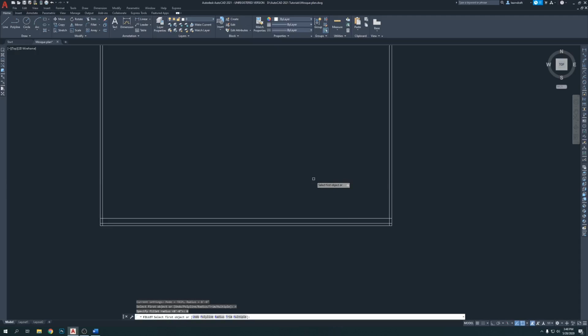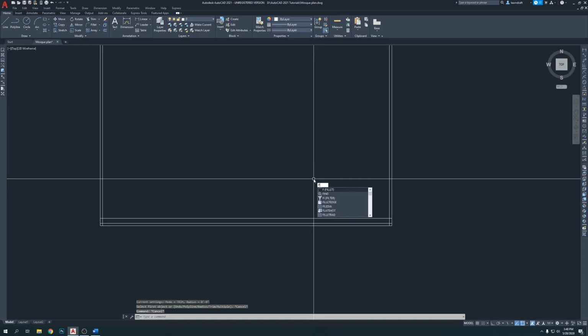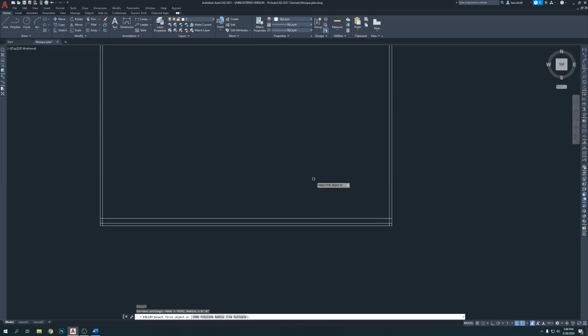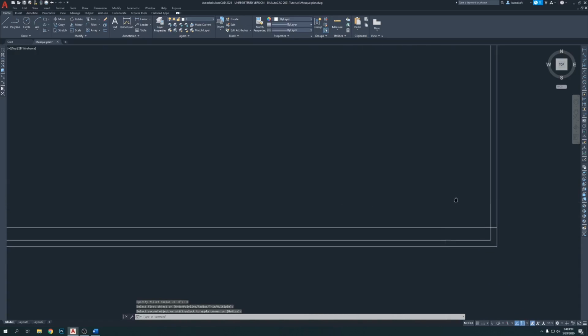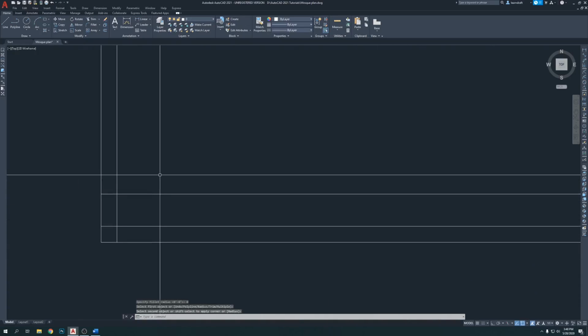Oh, I think I'm doing it very fast. Okay, fillet. Enter. F. Enter. Fillet, okay, from the beginning. So F, enter is for fillet. Radius, enter. 0 is selected, but I'm going to put 0 again. Enter. Now I'm going to click this line and this line, so the extra corner line gets cleared away.